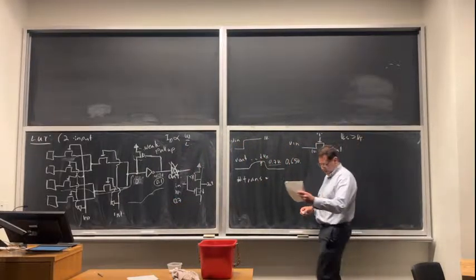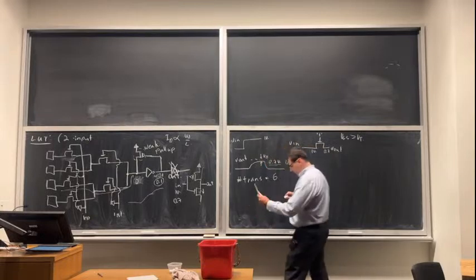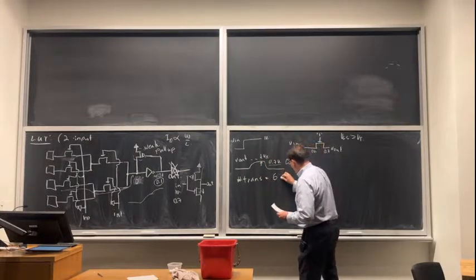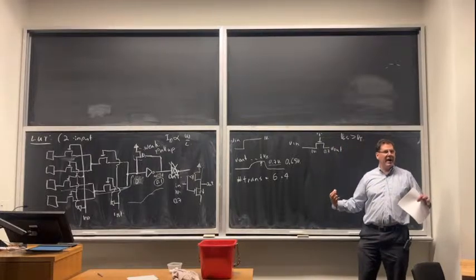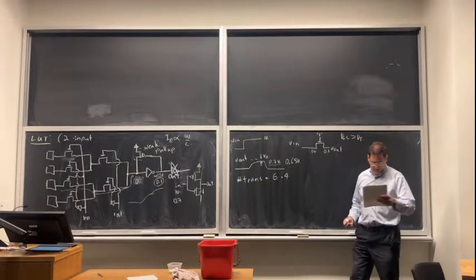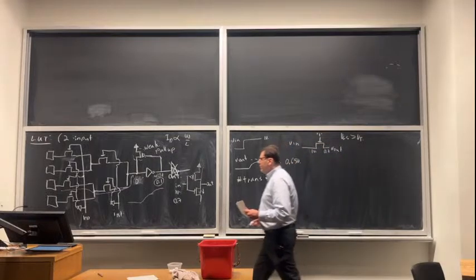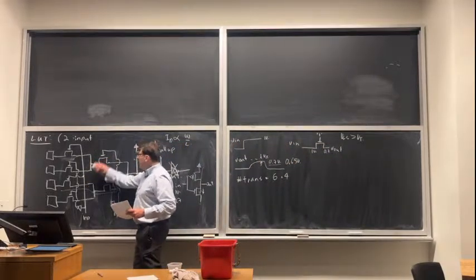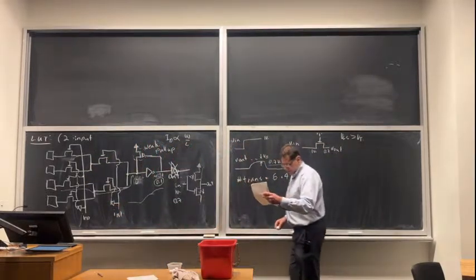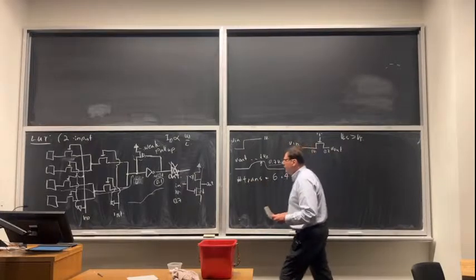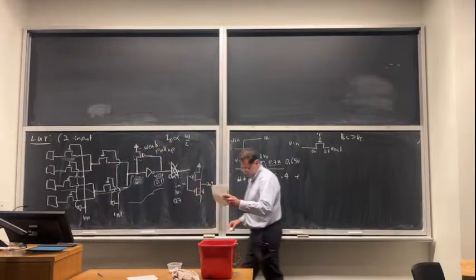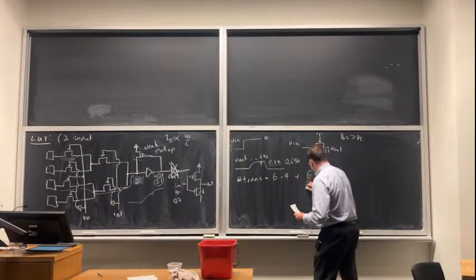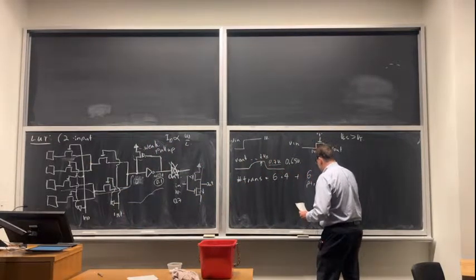We'll look at block RAMs in another couple weeks, so you'll see why that is. It's cross-coupled inverters plus a couple of access transistors. So an SRAM cell takes 6 transistors. And in this 2-input lookup table, I needed 4 of them. I also have 4 plus 2 pass transistors. So I have 6 pass transistors. This was SRAM.